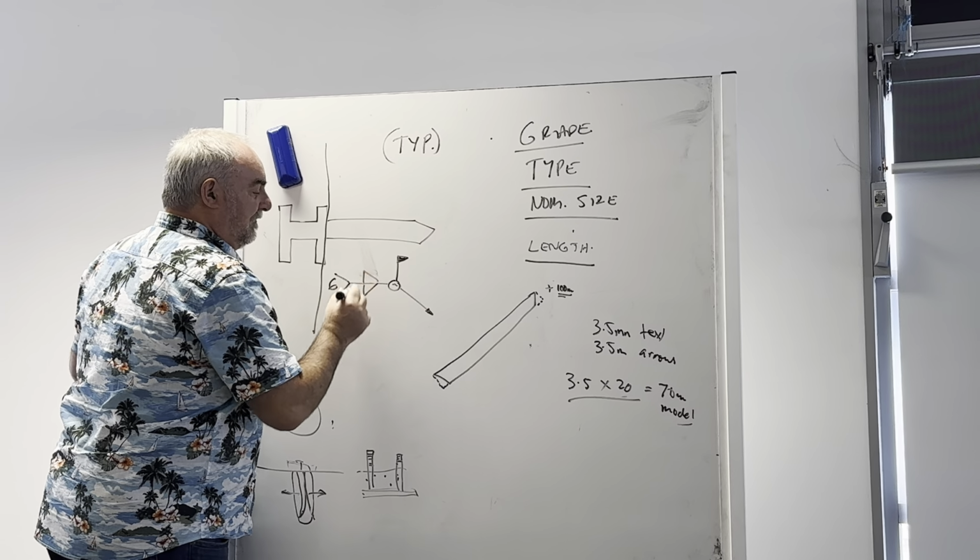And you need dimensions to the holes. You might have a hole over here, over here. You need to call up the holes, and you need to call up the bolts. And that's what it's going to look like. I can't do it all neat and tidy, so I'm pretty much just giving you something to copy for marks. These holes are based on your plate design, so you have your minimum and your maximum. You can't breach the minimum and you can't breach the maximum.